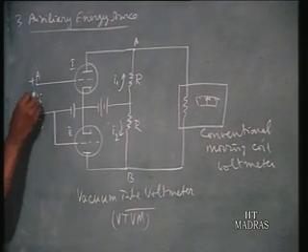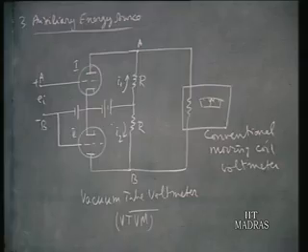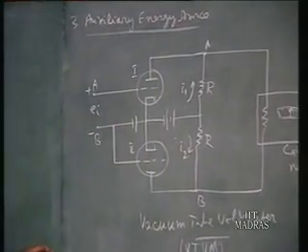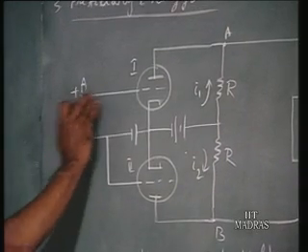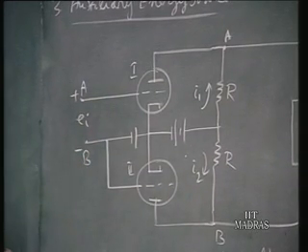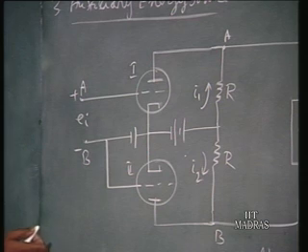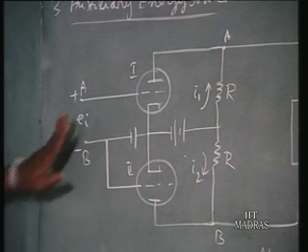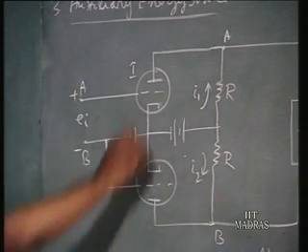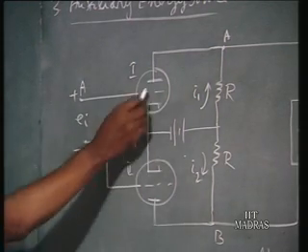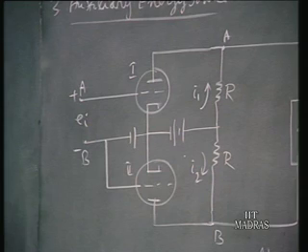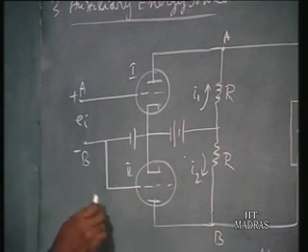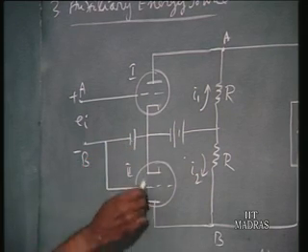Now this input voltage EI is given across the grid. We know grid to cathode is nearly an open circuit, so input resistance is very large. When resistance is very large, current flow will be of negligible value, in terms of microamps, a few parts of a decimal of a microamp, a very small value. That means the source is not loaded. But how is the circuit functioning? Consider the two triode tubes. The applied voltage is used across tube 1, and tube 2 has a constant grid voltage.